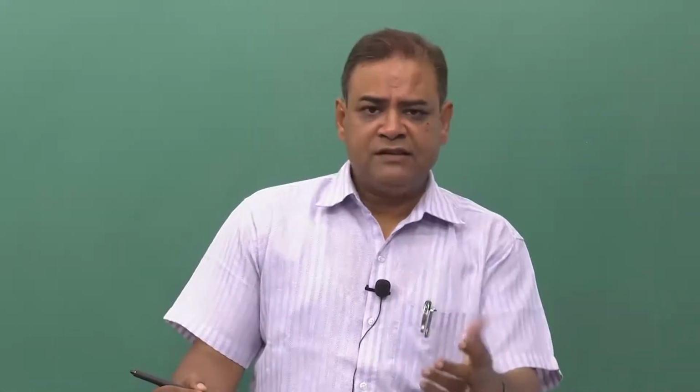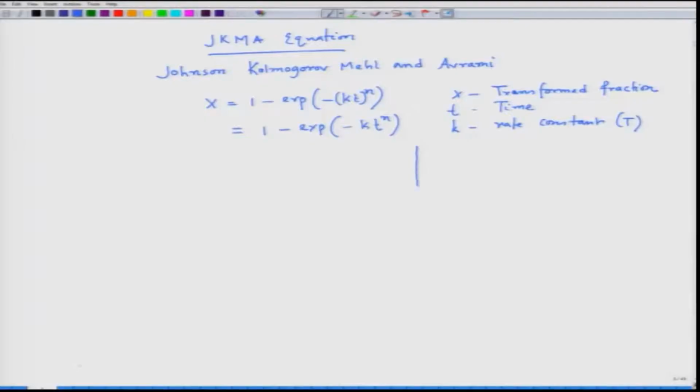And in order to explain this isothermal and non-isothermal case, for example, let us say you are at some temperature T and this is the time axis. One can jump to some other temperature below this temperature, and there one can hold the sample like this. This is the treatment called isothermal. And then another experiment can be performed where the material is taken to this level and then it is continuously cooled. And this temperature, in case of solidification, is to be taken to single phase.